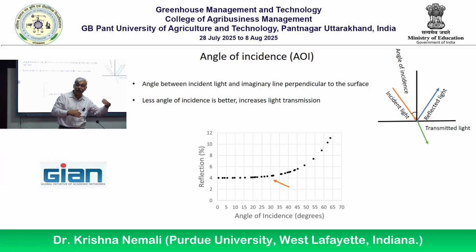When will light come at a low angle? Which season? In winter. In winter months. So your angle of incidence goes higher and higher in winter and becomes smaller and smaller in summer, regardless of where you are located. But depending on your latitude, it can even be higher in summer. Okay, depending on where you are. And that is why it is so important. So roof angle, the term for that is roof pitch or roof angle, is so important, so you can get away from that problem.